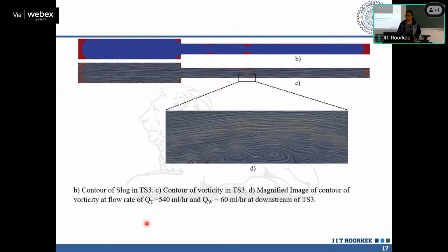If you recall the flow pattern map, what we have seen is the formation of a long slug when they encounter the sudden contraction. But what we haven't captured through the high speed camera is the presence of such waves, that is, the disturbance wave generated due to the sudden change in area from the vena contracta.